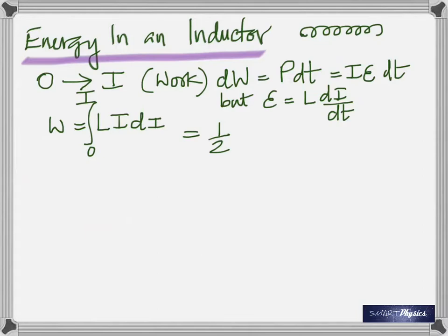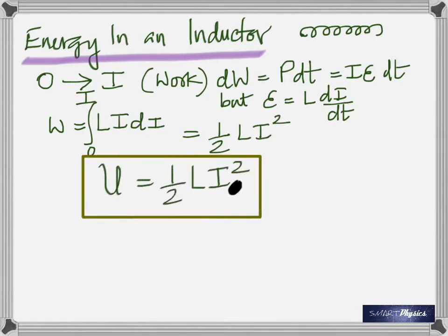So to find the total work done, you integrate from the limits 0 to I. What is the integral of Li di? Take the constants out. What is the constant? And then you have I di, just like x dx, and integral x dx is x squared by 2. That's it. So you have half Li squared. So the potential energy of an inductance is simply 1/2 times L I squared. Well, I put I naught here to show that that's the maximum current. Okay? Maximum current.